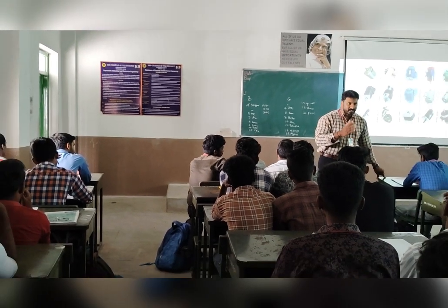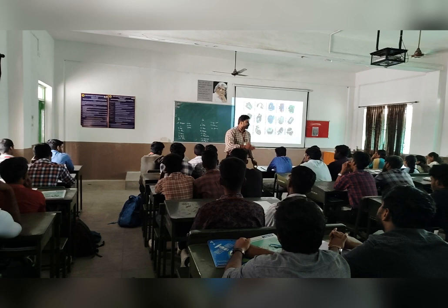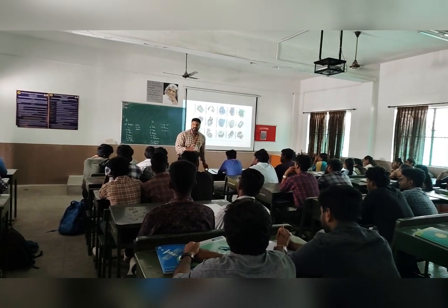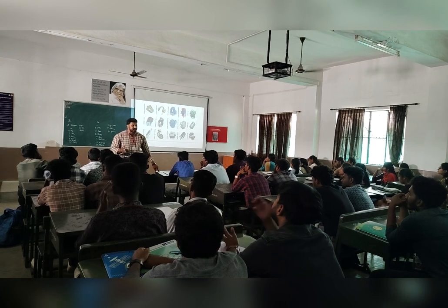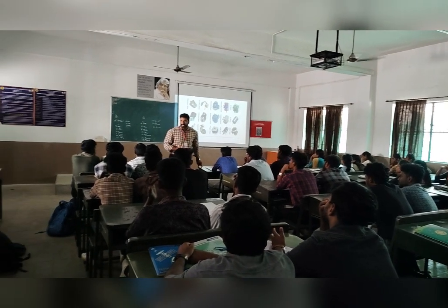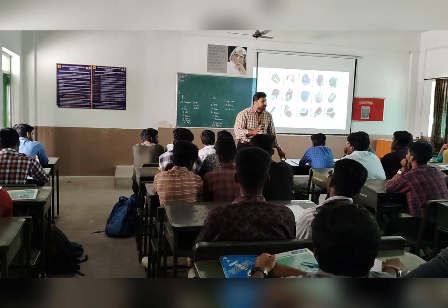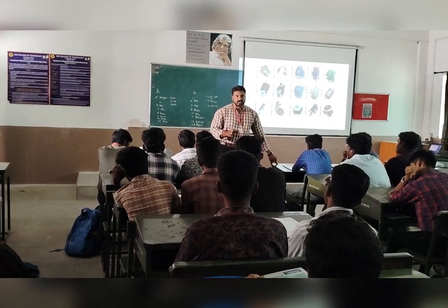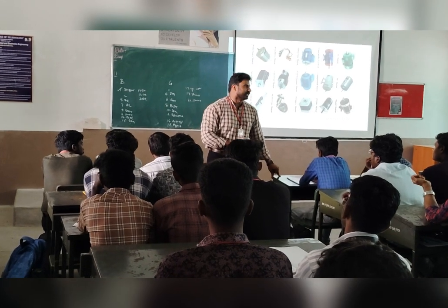We need to know when a motor needs a driver or not, and a capacitor or not. A three-phase induction motor doesn't need any kind of starting mechanism. But a single-phase induction motor needs some additional starting winding. A synchronous motor is not a self-starting motor. We need additional means, and there are different methods to start a synchronous motor.